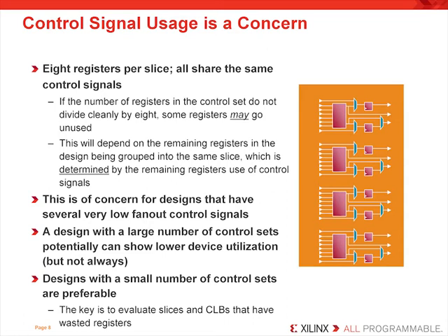This means that if there are 2 registers and both use the same clock and reset but different clock enables, then each register is forced to be part of a different control set and cannot be placed in the same slice. If these flip-flops cannot be grouped with other flip-flops with the same control signal set, then these flip-flops will be isolated in their slices and the remaining flip-flops will go unused. To be specific, control signals are, of course, sets, resets, and clocks, and a control set is a group of control signals that is used for one slice.